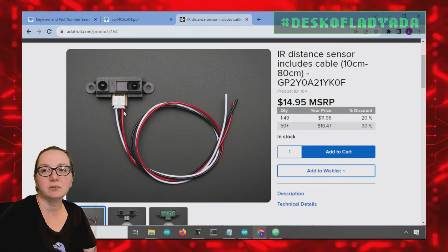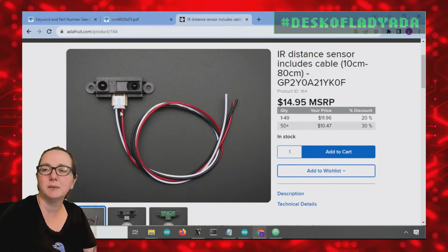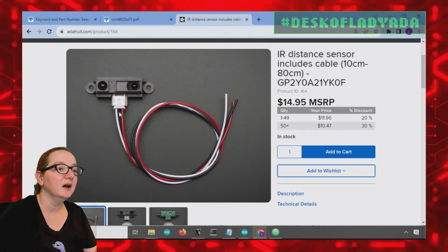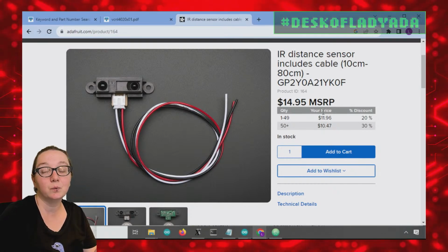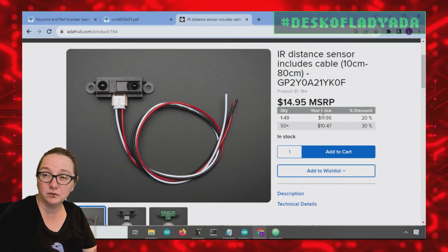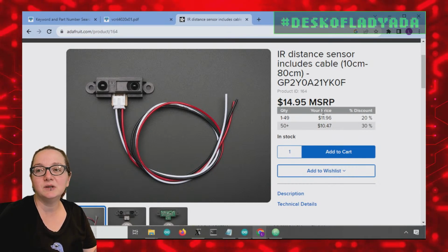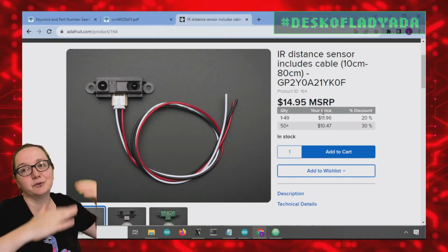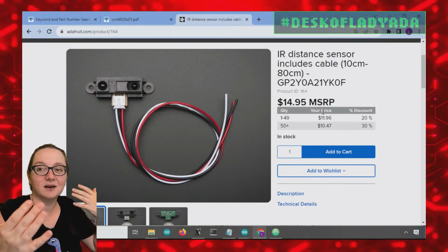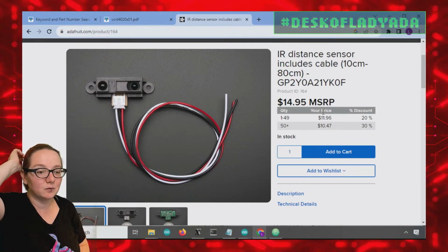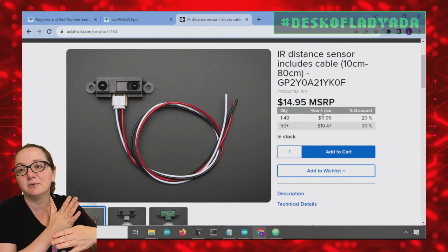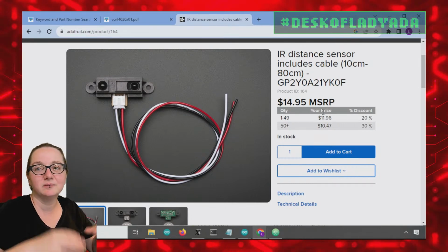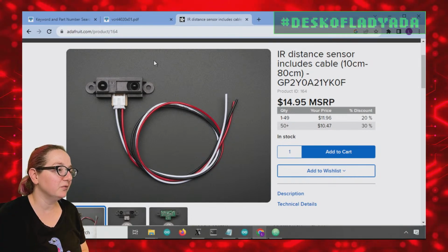So power is red, 3 to 5 volts, ground is black, and the analog signal back is white. This was a very popular sensor. In the beginning, when you didn't even have a microcontroller, you could hook this up to a comparator. When the analog voltage went above or below a certain value, you could detect that somebody is within this distance, or you could change the brightness by having the analog voltage feed into some other current amplifier. So these were very, very popular.